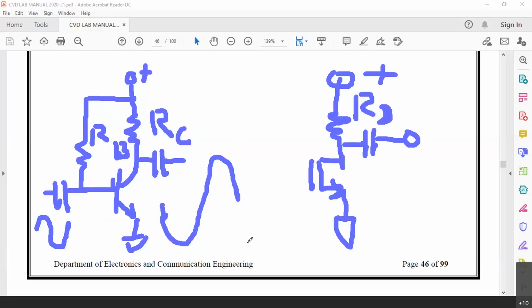Now, again at the input, we will give the input signal like this, and we want an output signal at the output. Now the point is, at the output, just like RC, you need RD. Because when the transistor goes into complete linear region, in the case of MOSFET, then the power supply should not be shorted to ground. And at the output anyhow, we need a coupling capacitance.